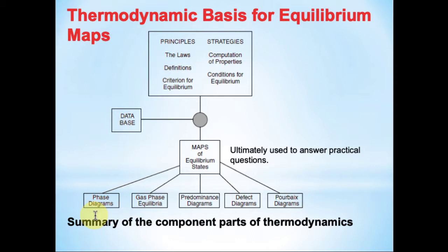A point in the phase diagram represents the equilibrium structure of a particular material composition at a particular temperature. The gas phase equilibria map displays the equilibrium composition of one of the components in a mixture of gases. This kind of map also provides the basis for the design of furnace atmospheres with control chemistry for heat treatment, coating formation, vapor deposition, and stoichiometry control.